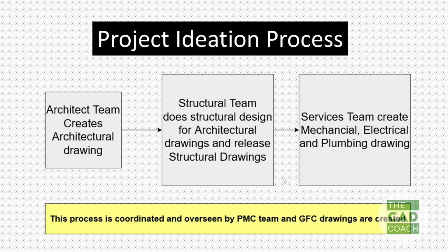So once the architect gives us a drawing, the architect drawing is changed to a structural drawing. The structural drawing is nothing but the built asset being ready. But in this built asset, the structural team and MEP team have to fix the services, that is, electrical fittings and plumbing. They have to design all those things and fit them to the structural drawing. So now the structural drawing is included with the MEP drawings, and all these three are coordinated